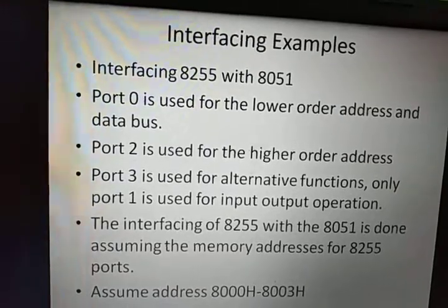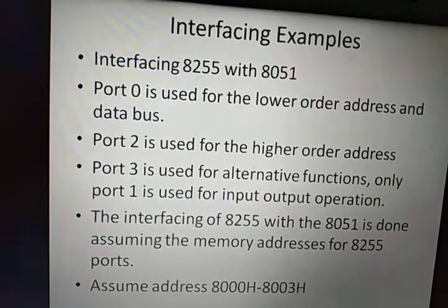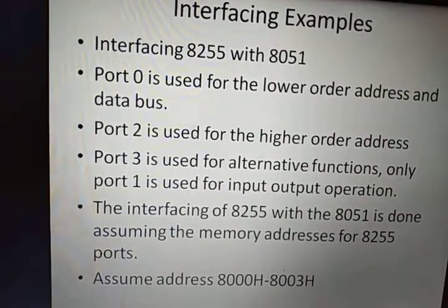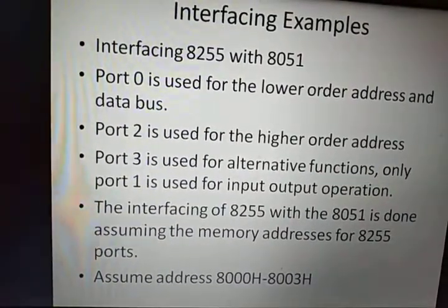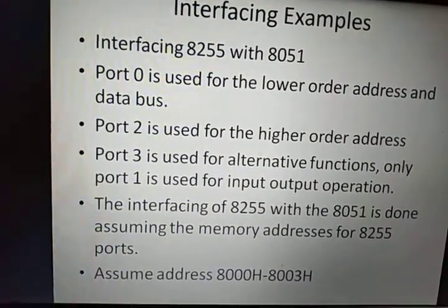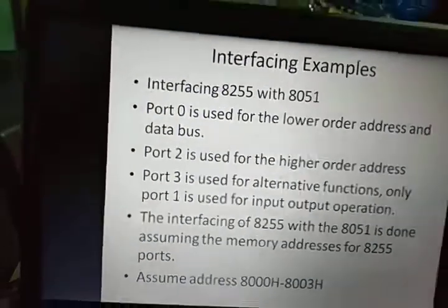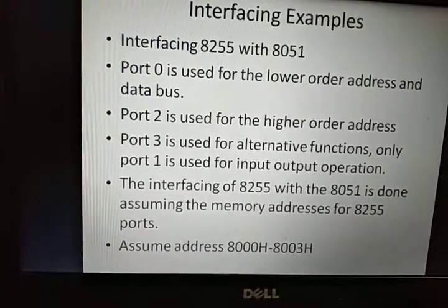So now we'll discuss interfacing examples. Under this we have three things: how the 8051 microcontroller interfaces with external memory via the 8255 ports, and how we are going to interface with the LEDs, switches and 7 segment display. Coming to the first interfacing example, interfacing 8255 with the 8051.